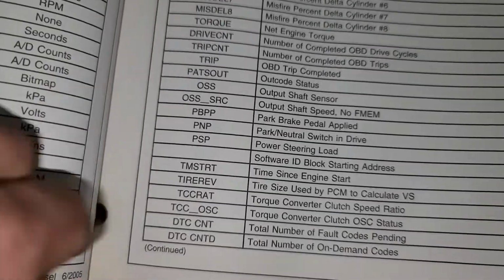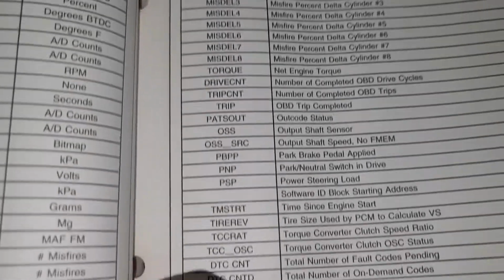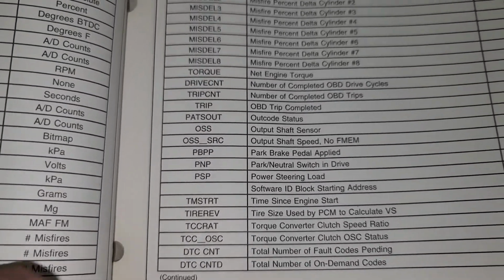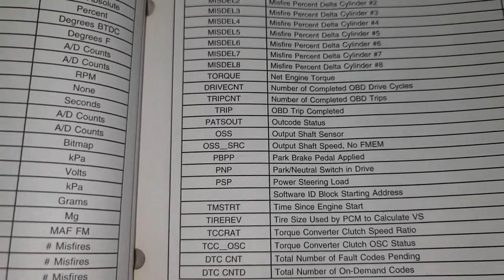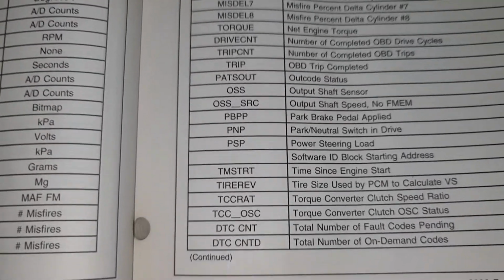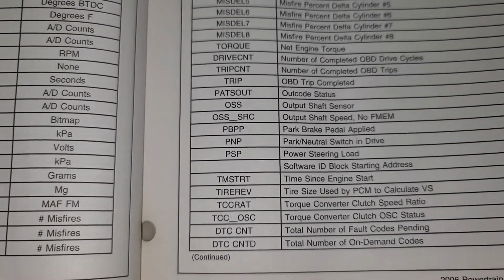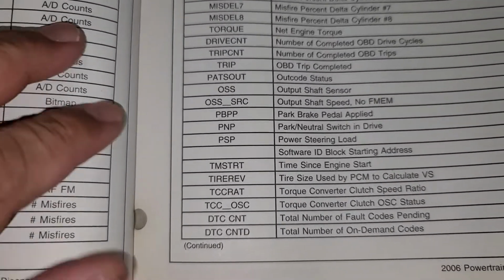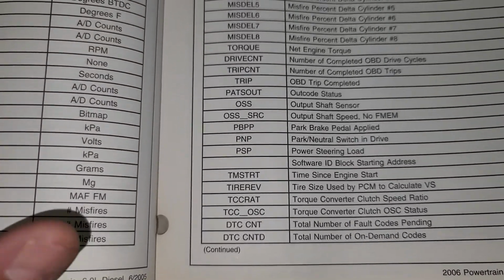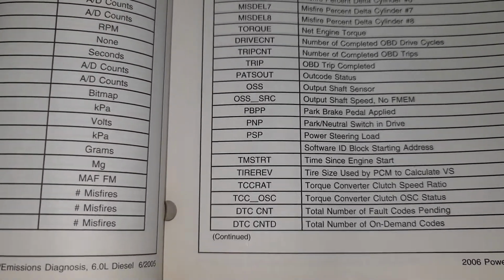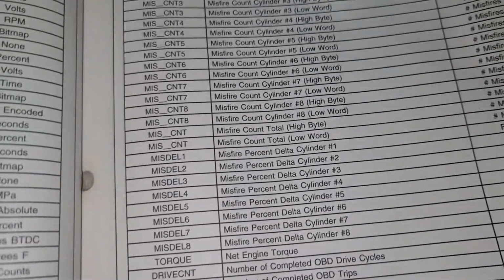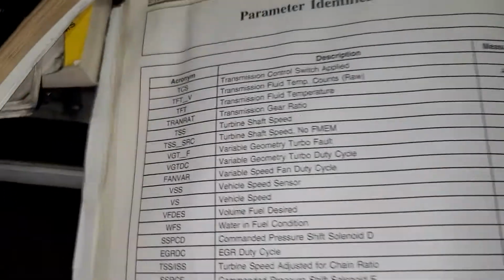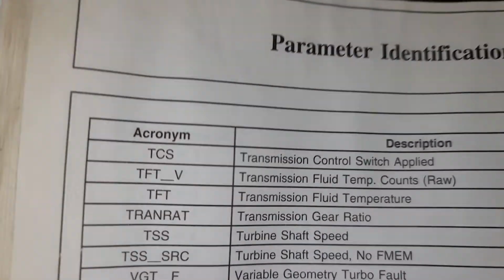DTC count. Everyone thinks, oh, what's a DTC count? You just go through it; sometimes it'll say there's 4 DTCs. Like if you use a generic code reader, like I said in my video, they were basically the same. I wasn't saying that the intake air temperature sensor and the mass airflow sensor were the same codes. What I was saying was the two codes that I got were basically the same as the next two, because it shows the factory code, and then if it didn't have the factory code, that's also a generic code for most vehicles, so it shows them again.